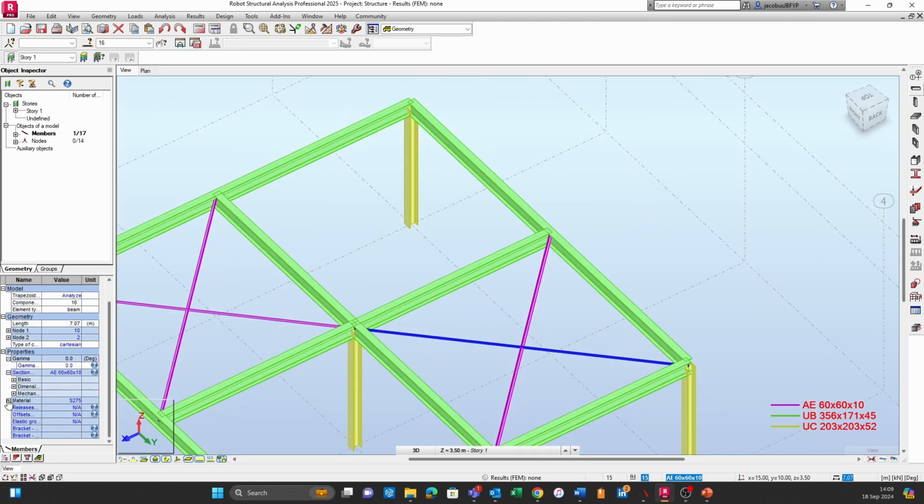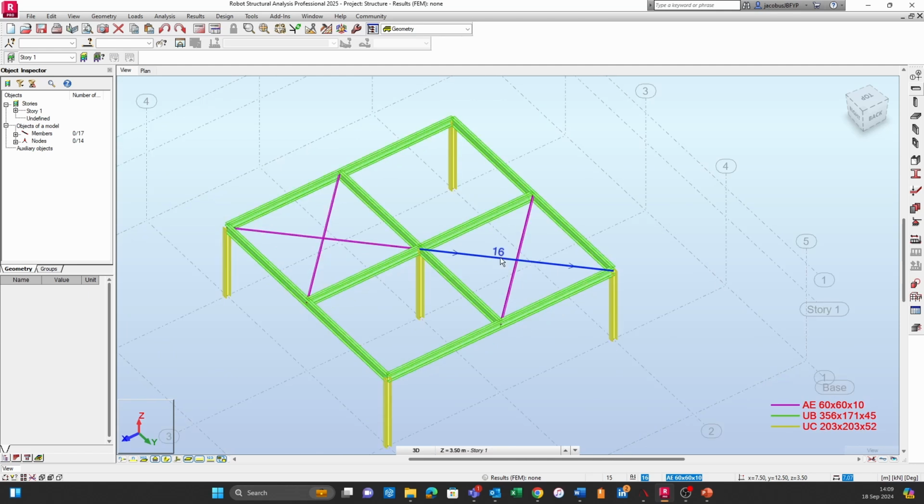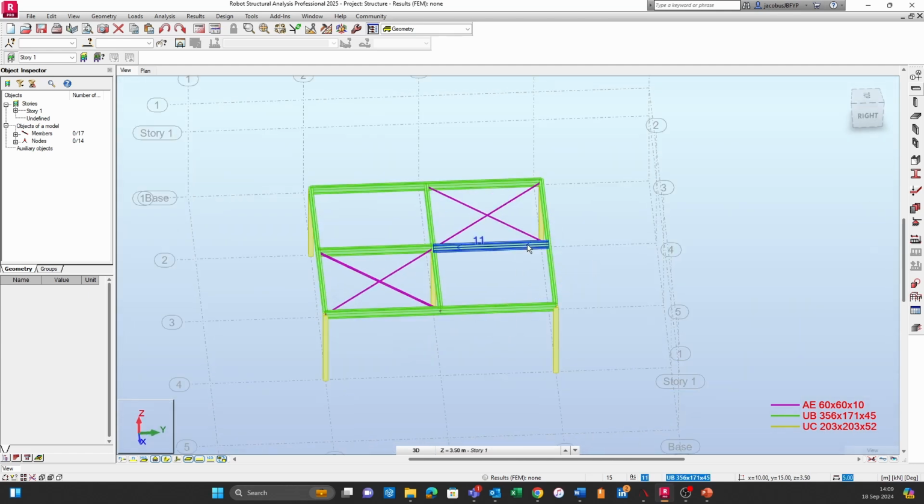All right. And here you can see some of its properties. And again, just because the cell is white does not mean that you can edit the data. All right, so just be wary of that. Even though those values are present here, does not mean that you can necessarily change it. All right, so this is just useful if you want to change the gamma angle, so the rotation of the member about its longitudinal axis. Right, and that really is the basics of adding members.